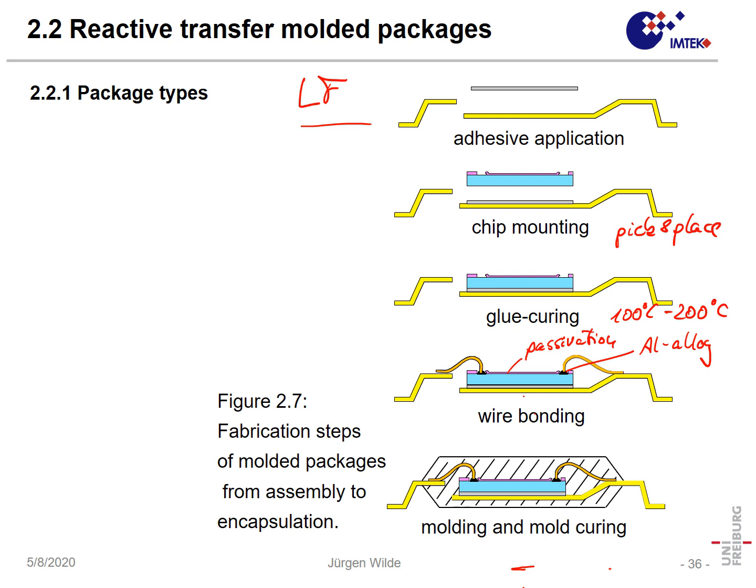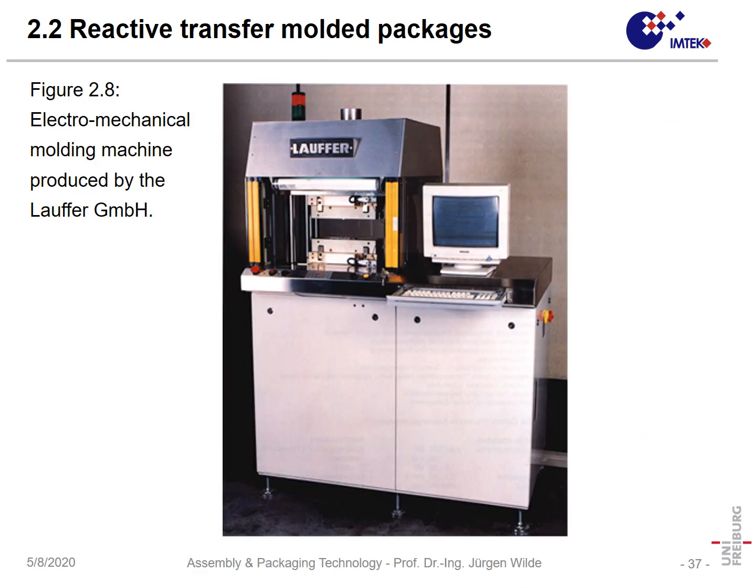And after we have accomplished this, we put that lead frame into a molding machine, and in that molding machine we inject some molding compound, and here is the molding compound. After that, typically the leads are bent again, and they are electroplated with tin, for instance, and in that way the package is finished.